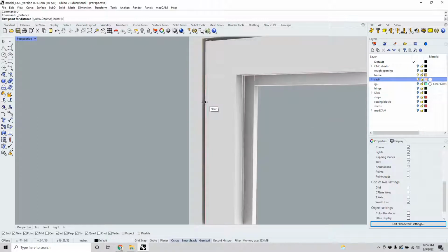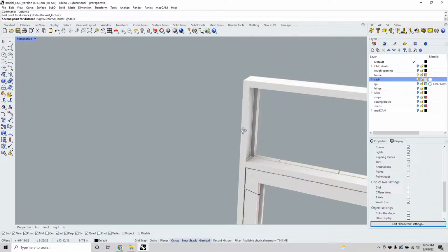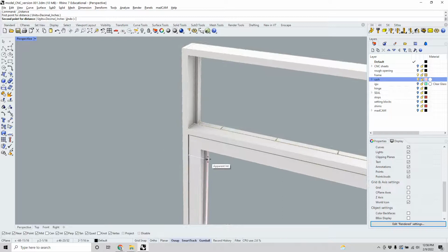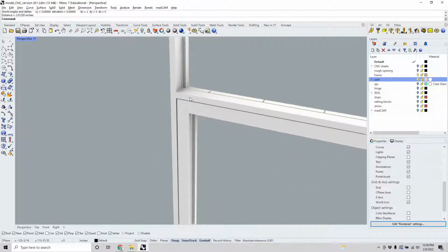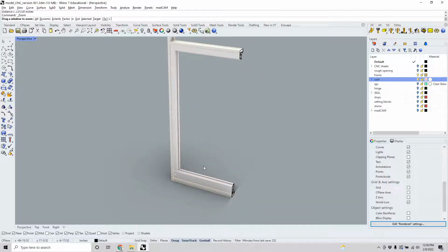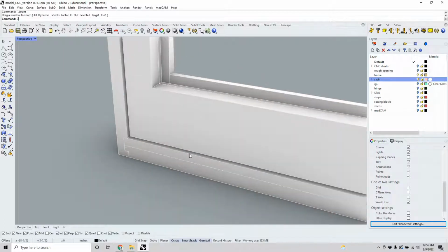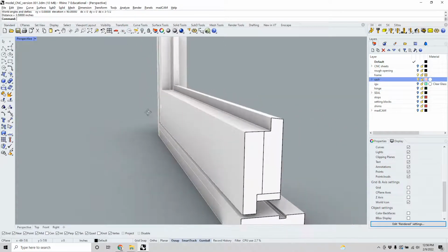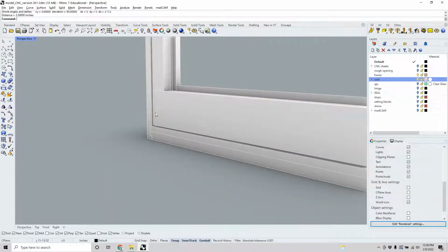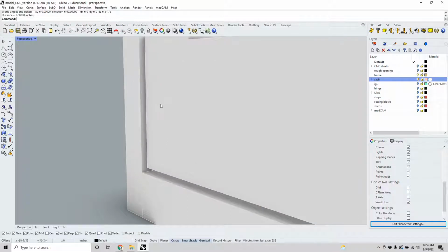The top dimension is approximately 2 inches because I'm working in millimeters now, so sometimes it's off numbers. The side is approximately 2 inches. Again, top and jambs are the same, and then the bottom piece is thicker. It is approximately 3.5, exactly 3.5. These two pieces are glued and laminated together, and I use these little 3/8 dowel pins in order for me to align the pieces together more easily.